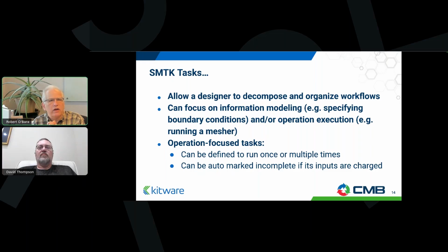Operation-focused tasks can be defined as a run once. For example, for those of you who are meshing, you might have a task that says, create me a surface mesh. You do that once. Other tasks might be something that you may run multiple times. The one that comes to mind, since I do know meshing a little bit, is mesh smoothing. So you can set tasks to do that. You can also set operation-focused tasks to auto-complete themselves, to mark themselves incomplete if any of their inputs have changed. You can also mark them to auto-complete if they successfully run.